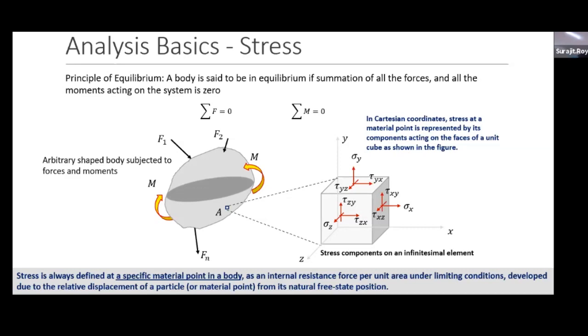There is a wide body of research and literature for conventional materials like aluminum and different grades of steel. There is a lot of catalog you can find and look at the basic properties, but you cannot find those catalogs for composite materials. For composite materials, every time you change a laminate sequence, you basically have different plies stacked together, and you cure it in a vacuum bag in an oven and you make a composite.